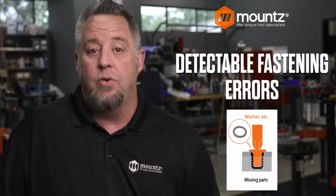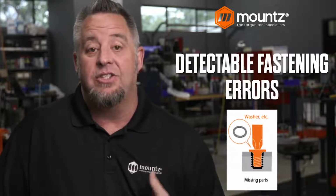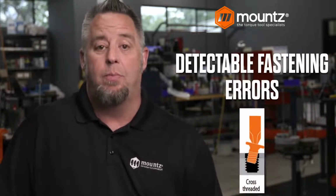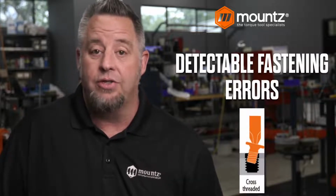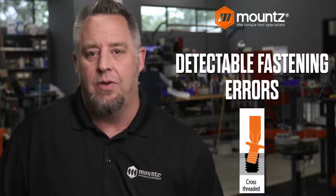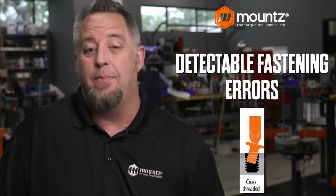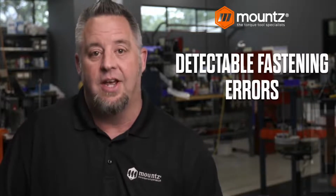If there are missing components, such as a washer stack or a gasket that needs to be in the assembly, we would be able to detect whether that is there or not. We can also help to prevent against cross-threading, or detect when a cross-threading event happens. That can be really helpful if you are dealing with very short fasteners, where the cross-thread issue may be very similar to a seating type of torque, but we can still detect that type of fastening error.